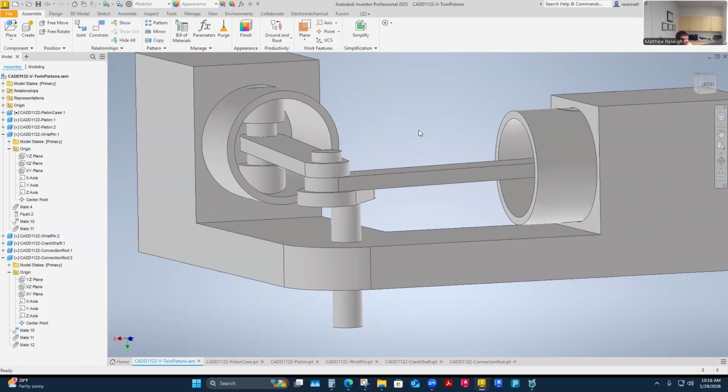So I think what I'll show you is my part that I handed around to you. If you want to pass it back around, look at it. It has these little things called snap rings, and they're a pretty common automotive part, like a hold-in-place position part. They're kind of cool because they can take a little force load. They can work as a little thrust. They are a spring steel, so they're a special material that allows them to thrust load, meaning they're meant to hold things in position, but if things rub up against them, they do have some strength involved.